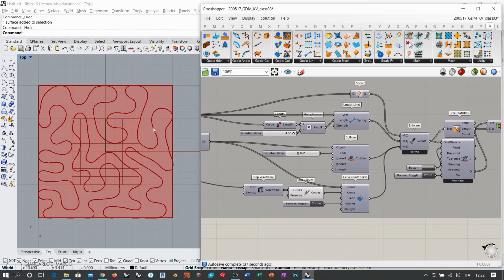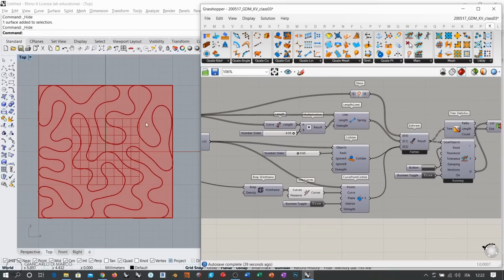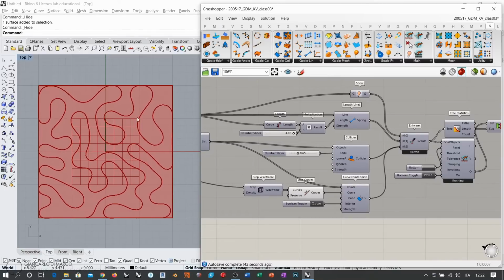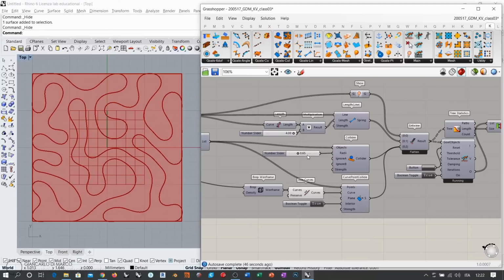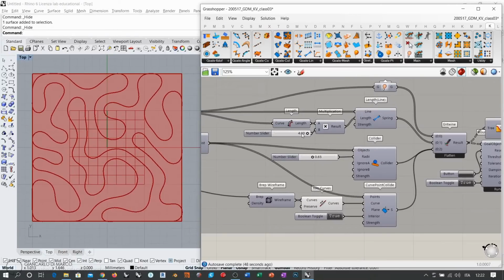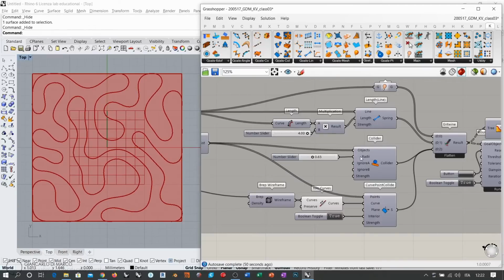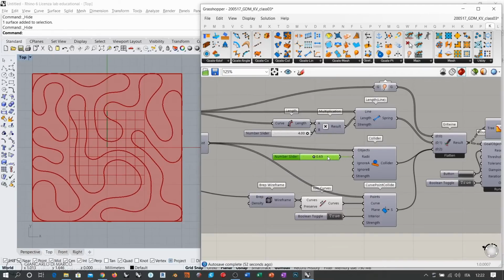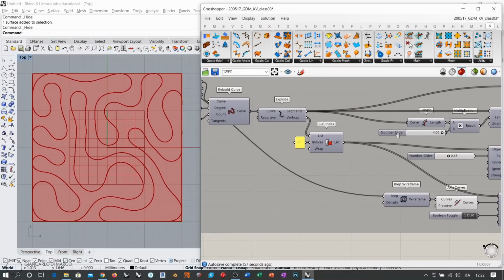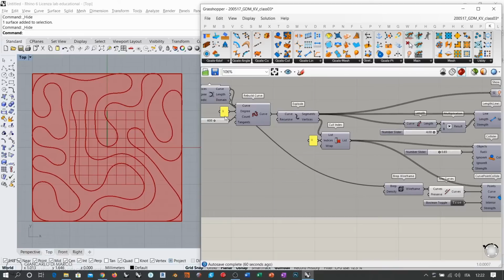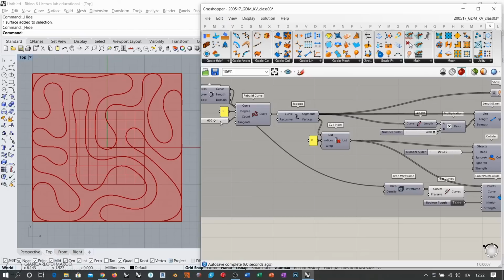Now, you saw that the expansion in this case was quite, let's say, fast. I don't recommend that you do this. This is because I left the multiplication factor to 4, and the radius for the collider is already receiving a high value for collision. Just so that you remember, we are using a closed curve with 600 segments.